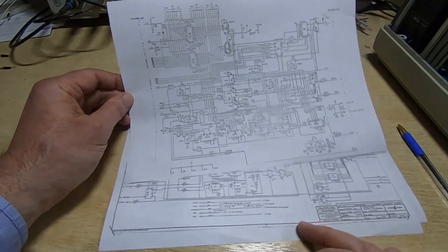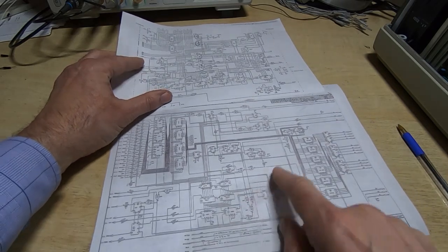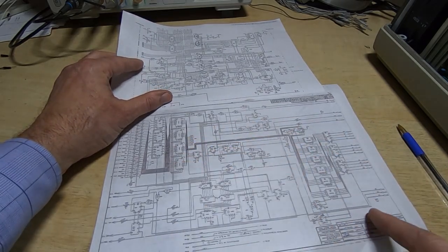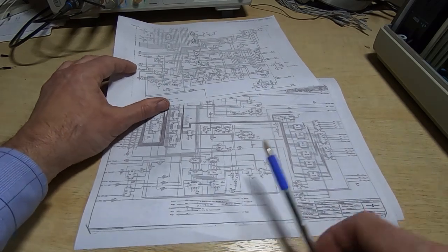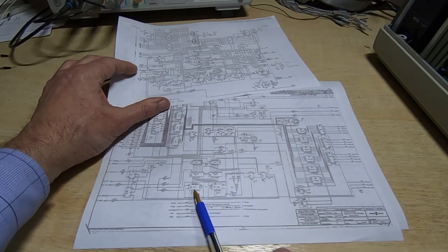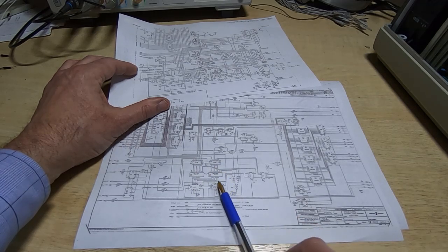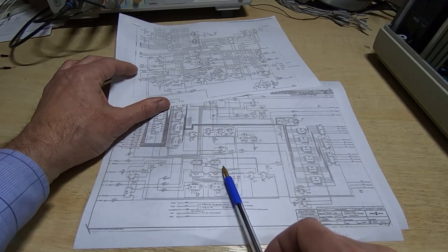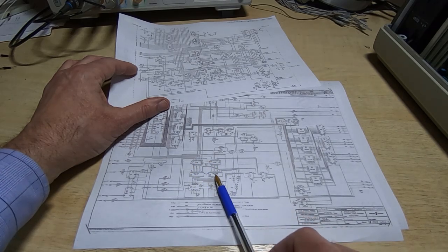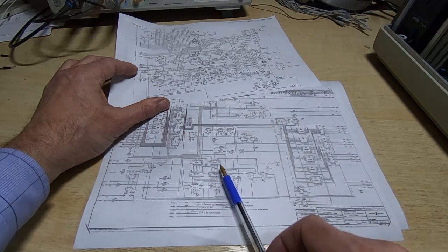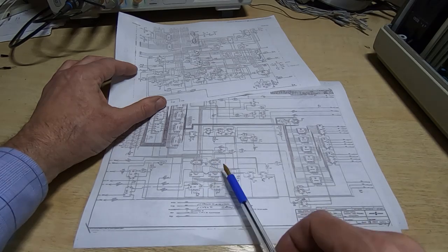When this is scanning, there is a state machine on the second of the two circuits we're looking at, and this is the circuit that's on the riser board that's in the leg that connects the monitor to the main unit. And there's a state machine in here that's comprised of a couple of PROMs, a couple of counters and some latches, and this goes through a sequence, and it's a bit like pseudo code that runs in these PROMs. It's very simple. It's only 32 bytes in each one, so that's 32 16-bit values.